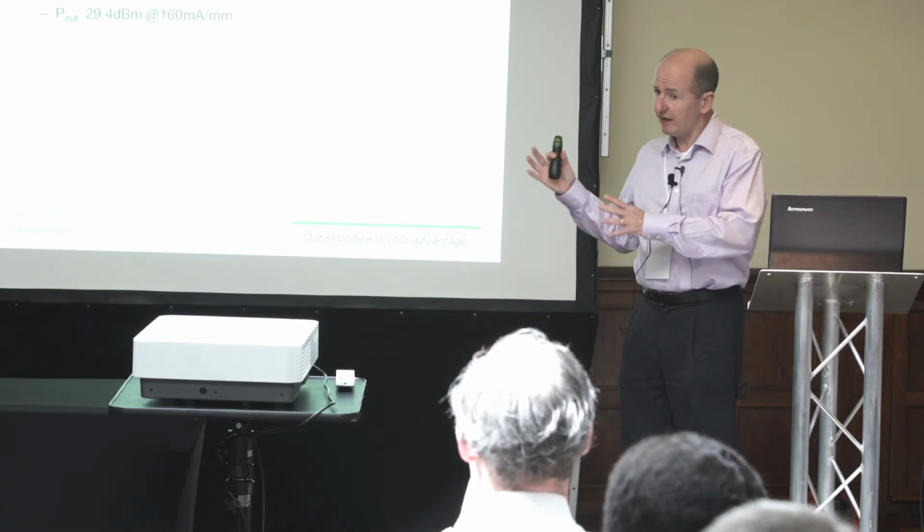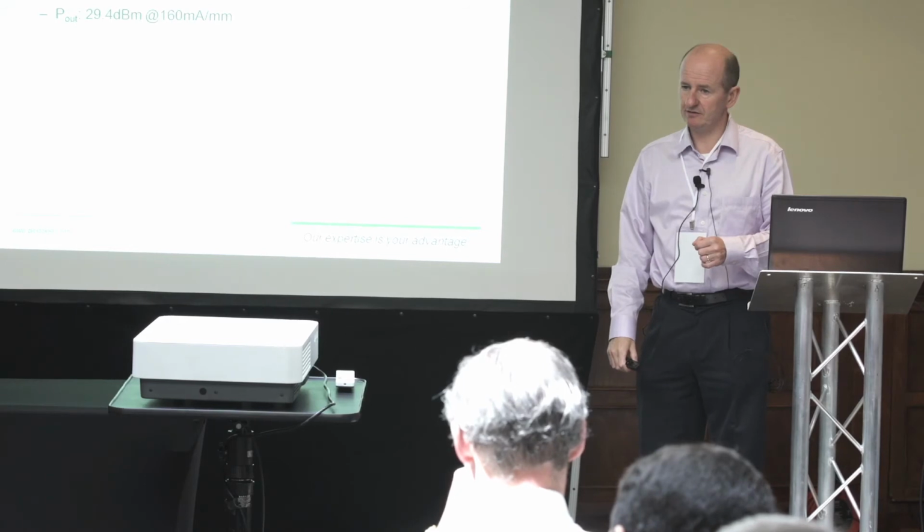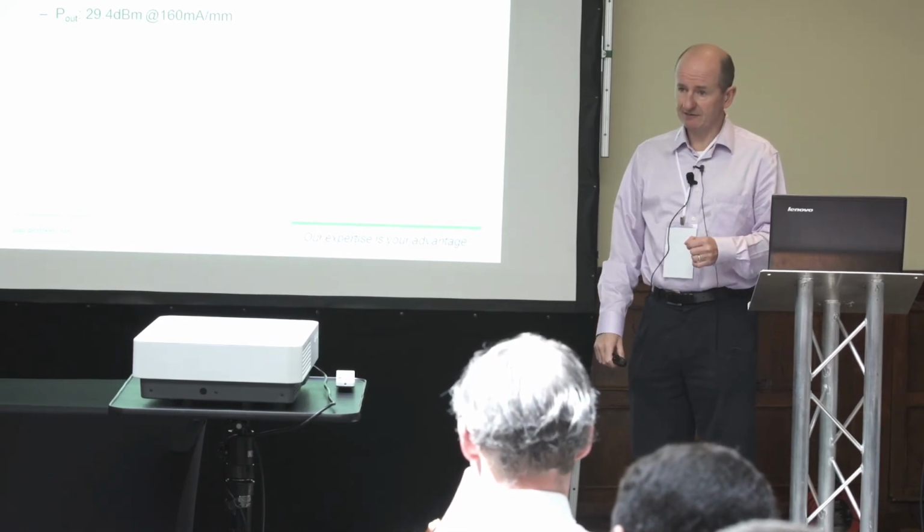So that's not actually an advantage of GaN, that's a disadvantage. Okay, but it is an aspect of the semiconductor. Right, it's a feature of the technology, yeah. I think it's just to add to the previous question. Is it in effect your P1 dB point is higher, so you're able to back off further to generate the same? No, it's actually the other way around. Your P1 dB point is actually a little bit further away from your PSAT.